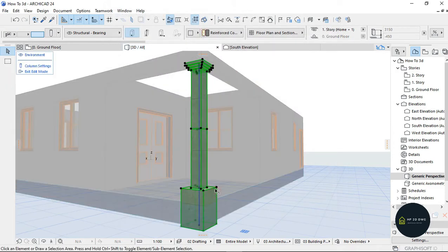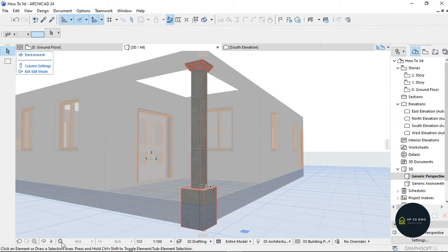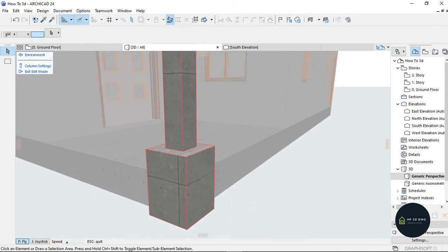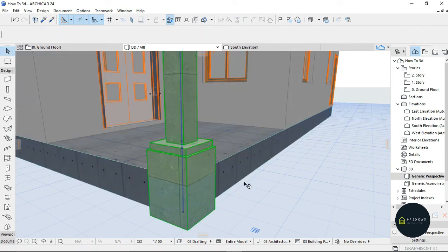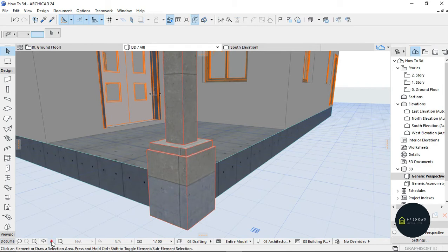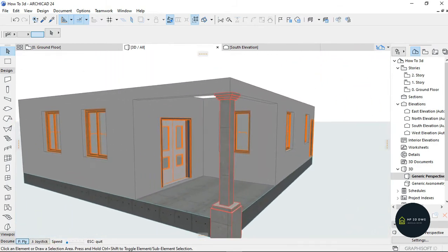Then I click on edit and click on this particular side, click on this node, drag it down to some reasonable height, zoom in so you can see what you're doing, click on it again, drag it down, and edit this to be, let me see, I want it to be 450, click enter, and you have your custom column that is to your own taste.